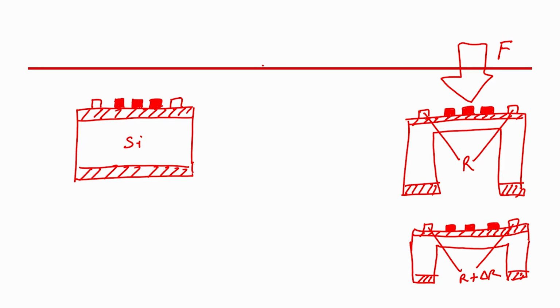Now, on this you have to form this one. So, what will you do? You will spin coat photoresist on the front and on the back. In fact, if you know that the material on the front will not get etched in the photoresist developer, then you can just leave it like this. So, now you have photoresist here.